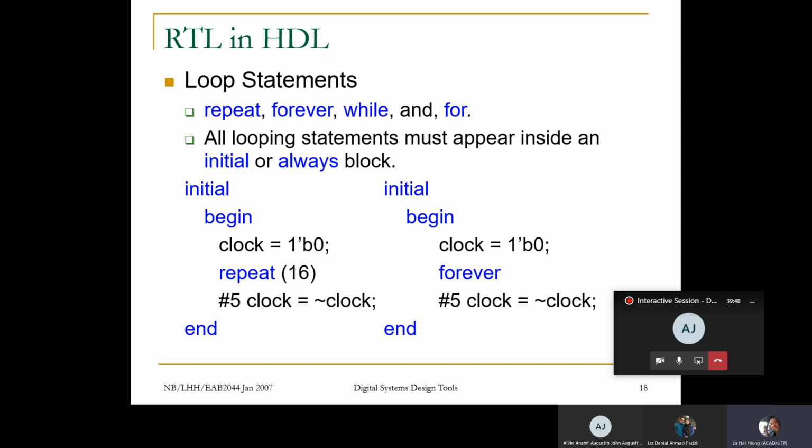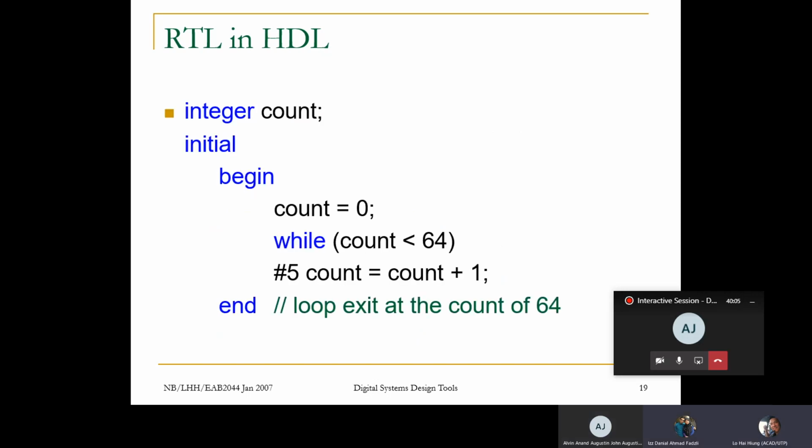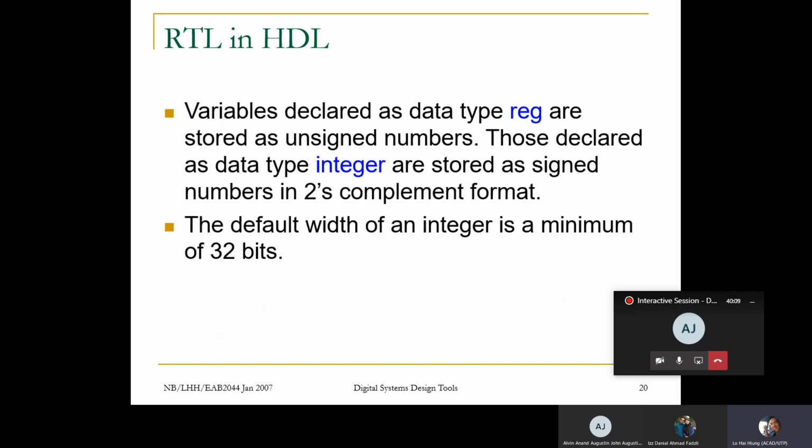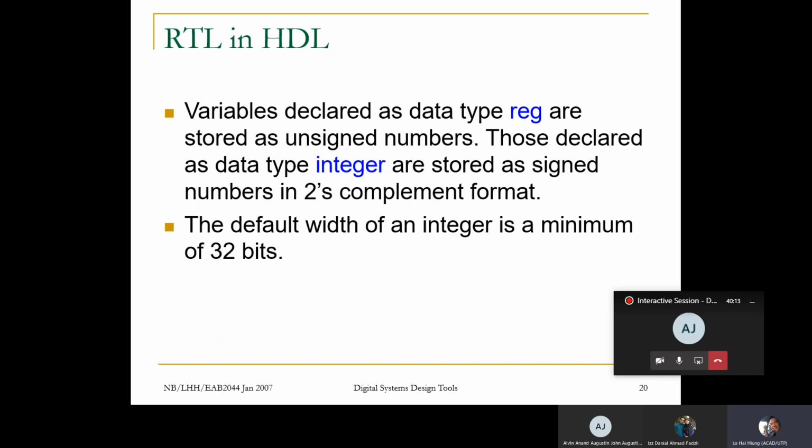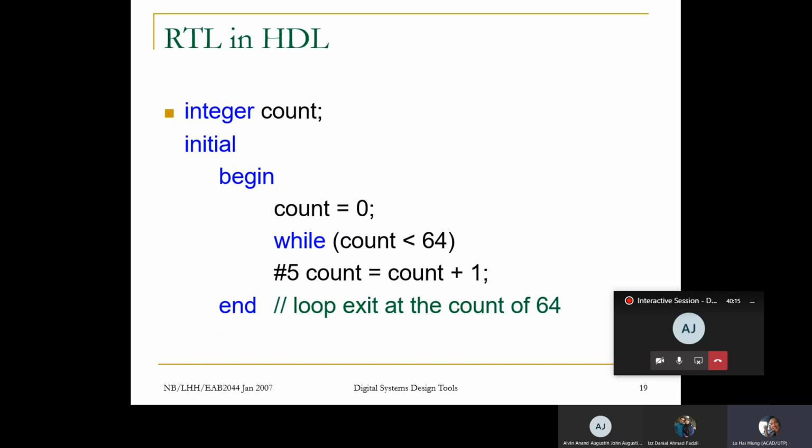That is the only syntax it accepts. So if you run into problems with your for statement, if you use i plus plus, it is not recognized in Verilog. All right? Is that clear? Yep. All right. So these are some examples of using all this looping. I will not go into it. I leave it for you to read, and you can copy this and try it out.